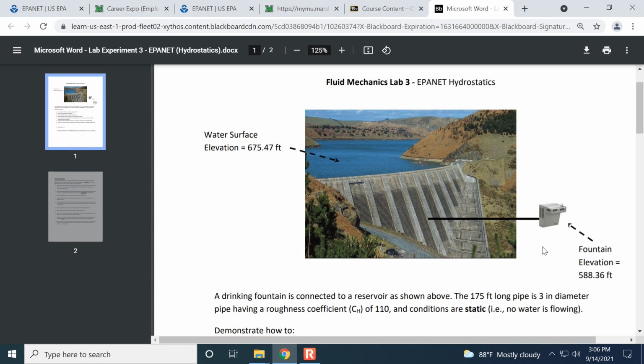Okay, so do that if you've got your calculator handy. 5436 divided by 144. I get 37.75, and I'm going to write that as PSI, meaning pounds per square inch. Okay, so now we've solved this hypothetical setup just using the hydrostatic equation. And we're going to use that as a reference when we try the same setup using today's software.